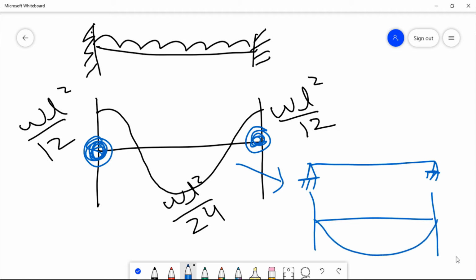Okay, at this support the beam loses its capacity to resist the moment. Now all the moment from the supports transfers to the center. Now the beam will behave like a simply supported beam after yielding. Again at the center the moment will be wL squared by 8. After forming of the hinges, this is converted into a simply supported beam.